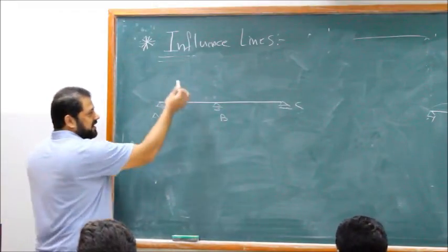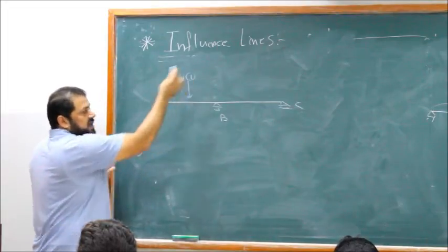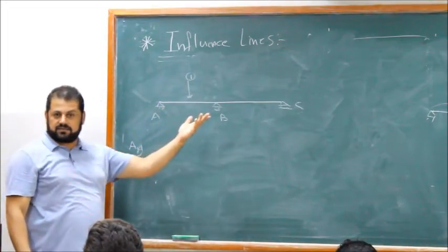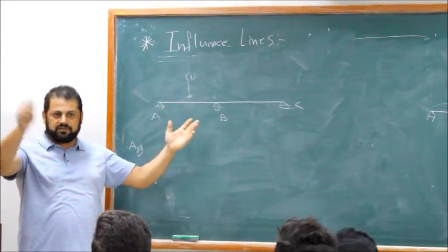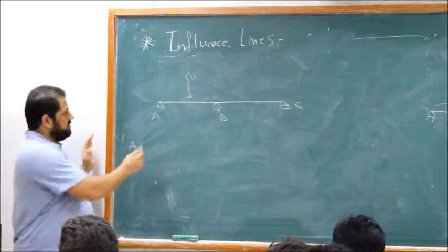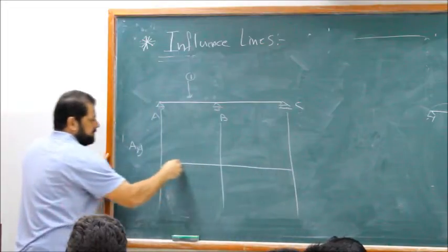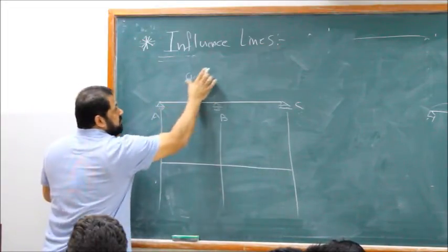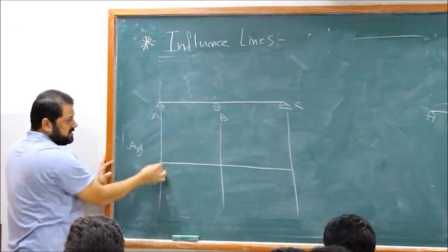At each location, we are solving a statically indeterminate structure. And if I give you one force or any force here, calculate the reactions, this is a question in the exam maybe. You remove one redundant, you put that redundant, you do the equilibrium. We know how to do it. This is exactly what's happening. Look, we're drawing the influence line. We move the unit load. When the unit load is right there at the support, how much is AY?